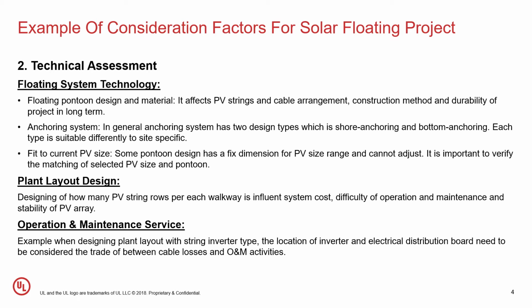Or when talking about material, one supplier may provide pontoon with HDPE material only, but others may provide the floating system with a combination of steel and HDPE. All of this will affect your cable arrangement, design, and losses, your construction method, and durability of the project in the long term. That's why it's very important.